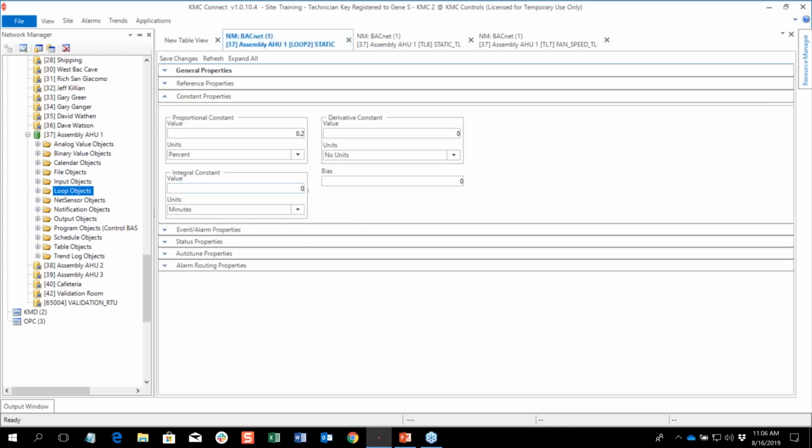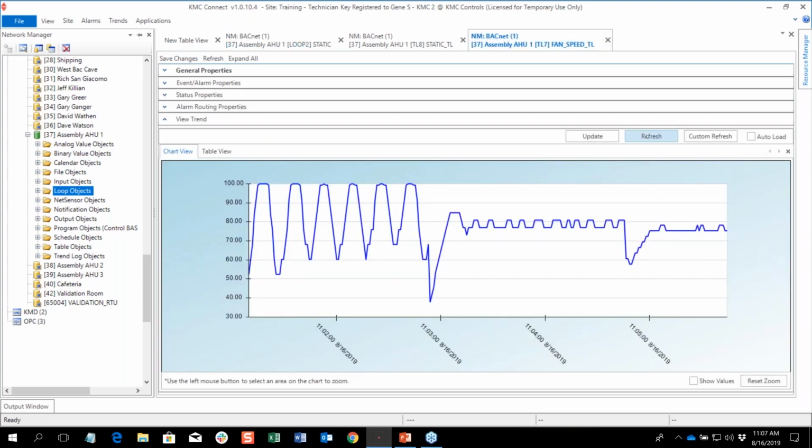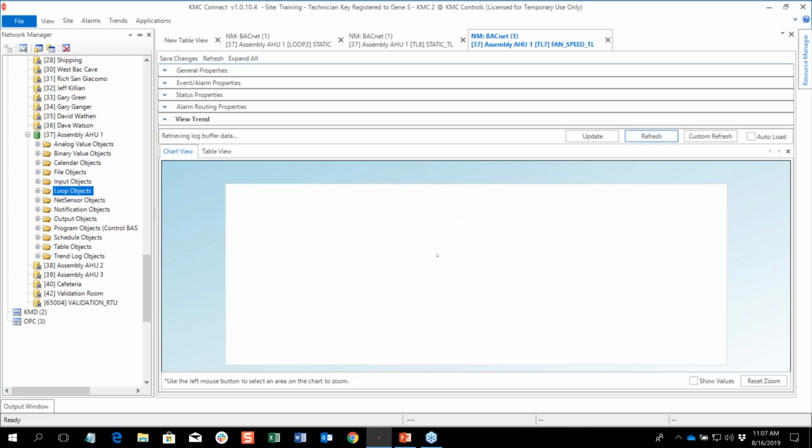So proportional is stable, but I still have error. Yep. So let's put a 0.1 in here once, see what that does for us. As we're looking for this integral response, I kind of want to touch back on why, with proportional only, do we have steady state error.